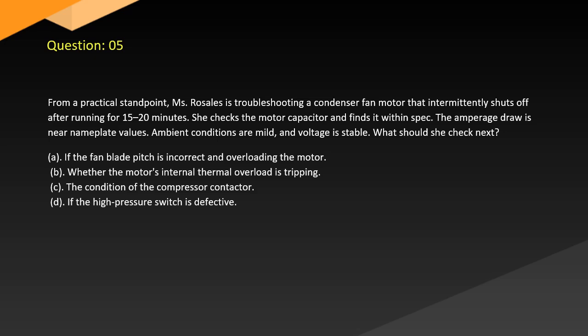Question 5. From a practical standpoint, Roselle is troubleshooting a condenser fan motor that intermittently shuts off after running for 15 to 20 minutes. She checks the motor capacitor and finds it within spec. The amperage draw is near nameplate values. Ambient conditions are mild and voltage is stable. What should she check next?